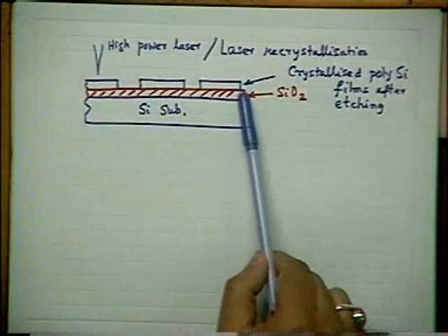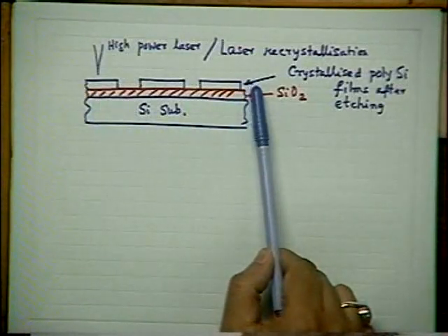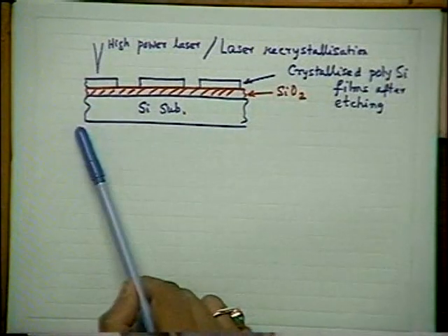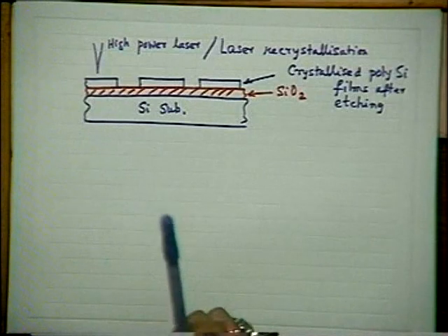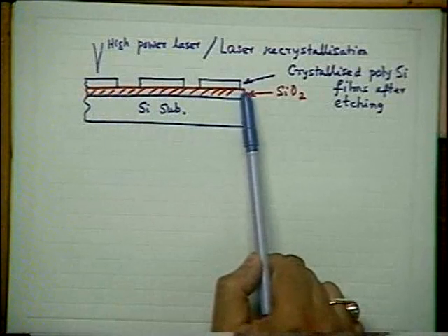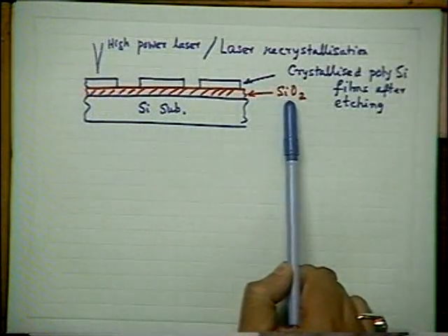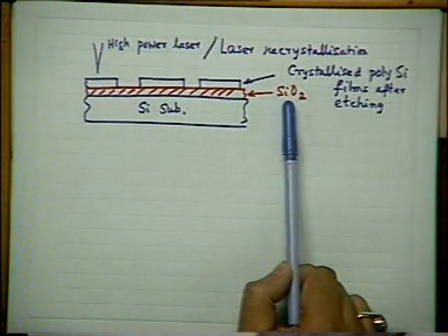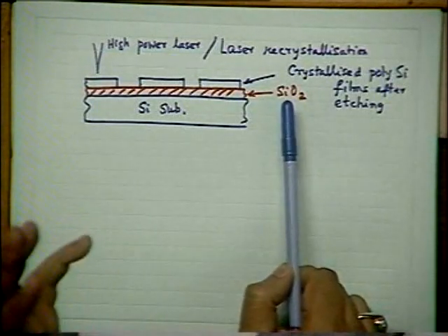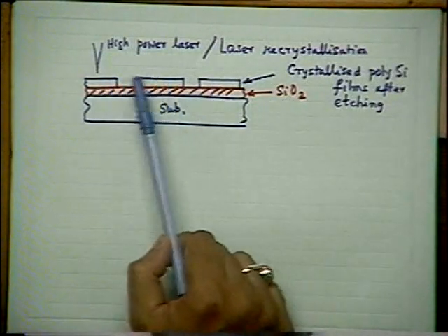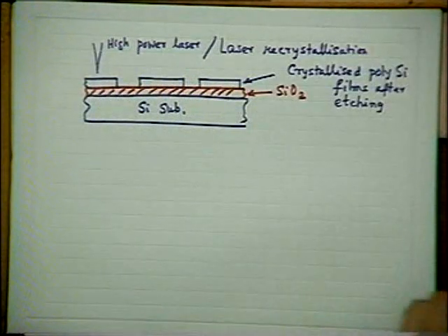And ultimately the same thing, only difference between this one and the earlier one, the SOS, is in the SOS the whole thing was sapphire. Now it is mostly a silicon substrate, a low cost material. The silicon substrate is a batch production technique and the cost wise is much smaller. Then we have a separation of a dielectric film, a very good quality dielectric silicon dioxide. Its resistivity is very high, very low loss material, up to very high frequency. And on the top I have these silicon islands, and in each island we have our components, and we can do the similar IC processing to finally get our final IC, final product.